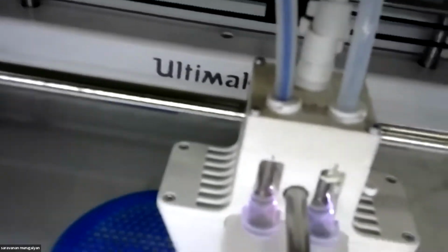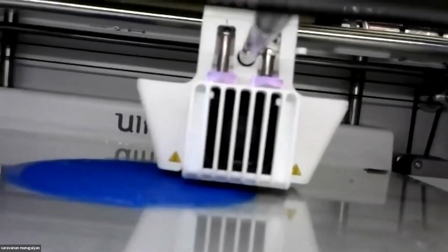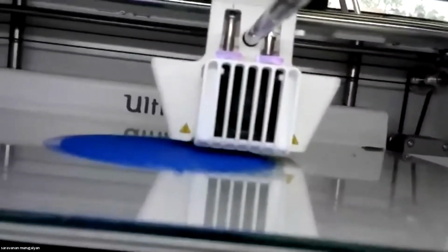After the material enters the extruder, it passes a heater and a cooling fan. The heater of the extruder is maintained at a temperature of 200 degrees centigrade, which is necessary to completely fuse the polylactic acid into a semi-solid state. As soon as the material reaches the semi-solid state, the extruder pushes the material through the nozzle, and the material from the nozzle gets deposited onto the surface on which we are printing the component.